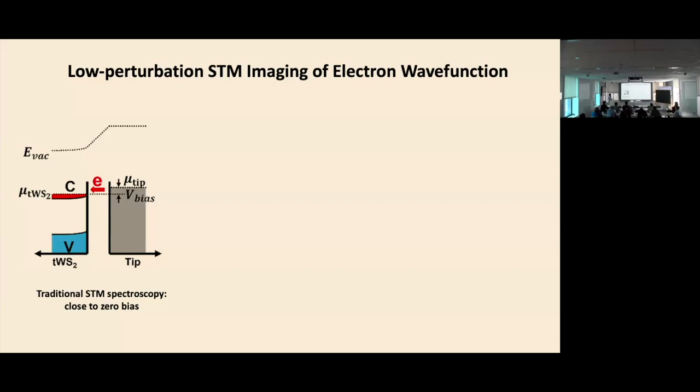Because they have very different work functions, the vacuum level will be very strongly offset. That means there will be a very strong band bending, and a very large electric field between the STM tip and the sample, which creates the band bending in semiconductor physics, like the Schottky barriers.